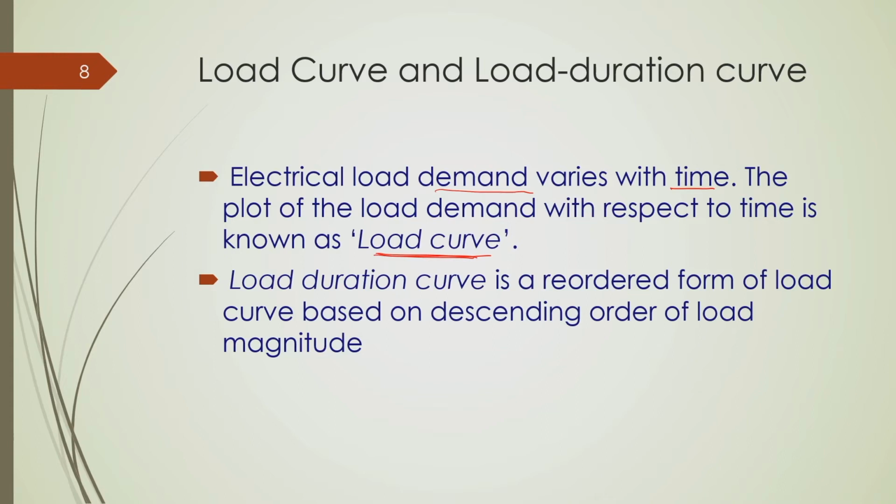I will show these plots in the next slide, but suppose I have a residential area, or rather a small distribution network, and this is the power demand and this is the time, starting from 12 o'clock midnight to 12 o'clock midnight of the next day. Then I determine the instantaneous power demand throughout that particular day and plot it.